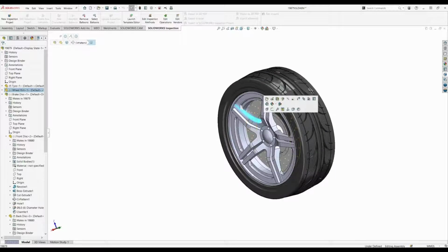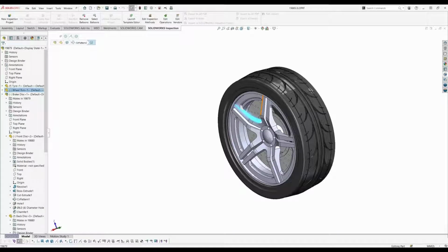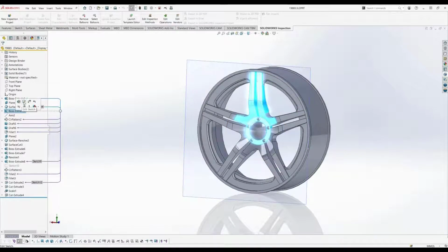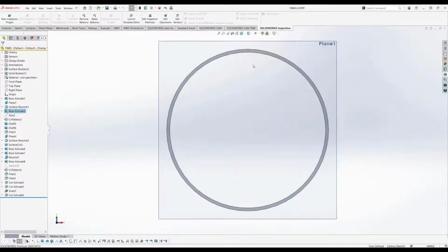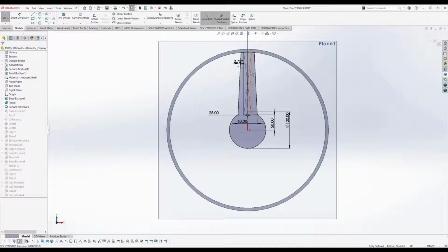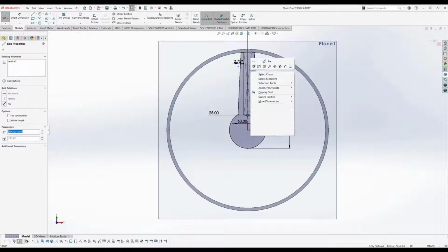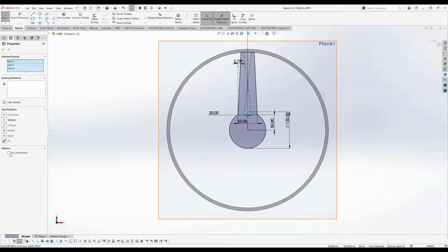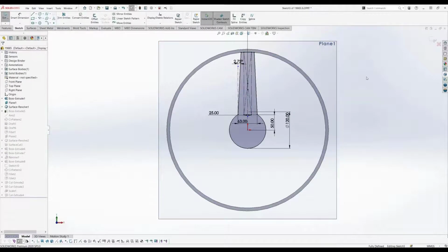So now we'll get into the component part and take a look at how to make a change just real quick to the rim itself. There we have it. So the original extrude included the cut, and so we will need to make adjustment to the original sketch for this, but it is very easy to manipulate and make the changes necessary. In our new design, it has a wider stance. It also is a consumer grade, where this one may have been a racing grade. So we want to eliminate any weight reductions that may cause a problem when someone hits a curb. So that's kind of our premise, and that's our idea for the change.